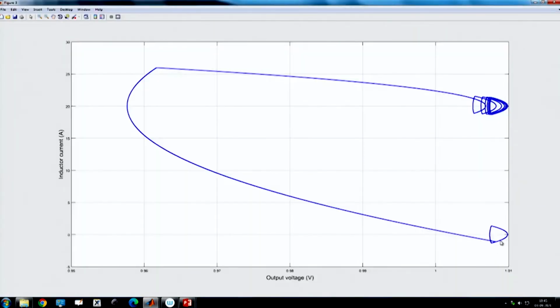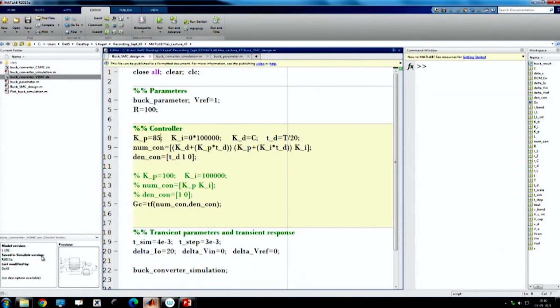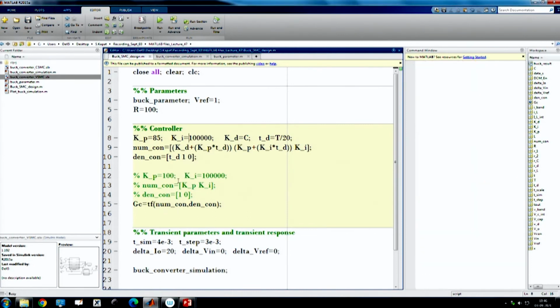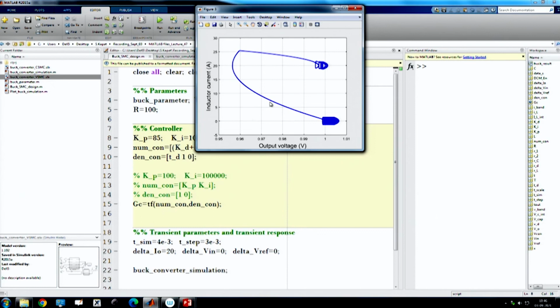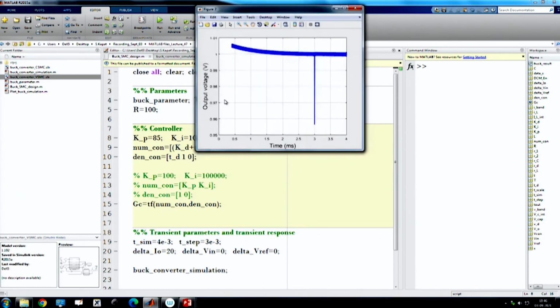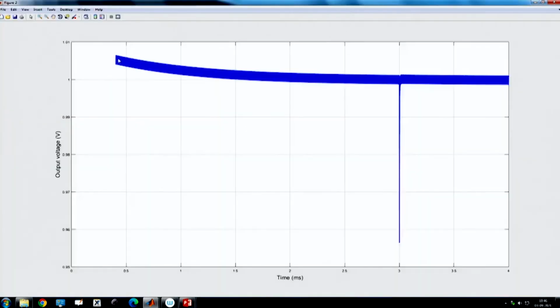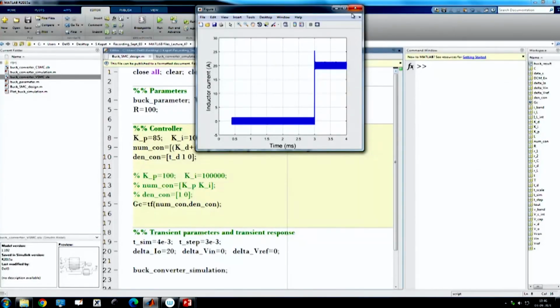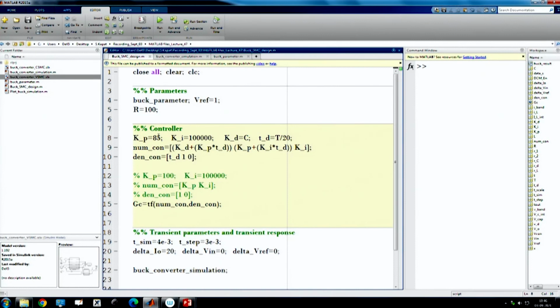and you will see that it is almost coming to steady state, but there is a steady state error because it is shifted by almost 10 millivolt, and if we want to eliminate it, let us enable the integral action. So, then it will make sure that there is almost no steady state error. Okay. So, we have enabled the integral action now. So, it is coming back and we are coming close. So, we can further increase, so we can do like 90.